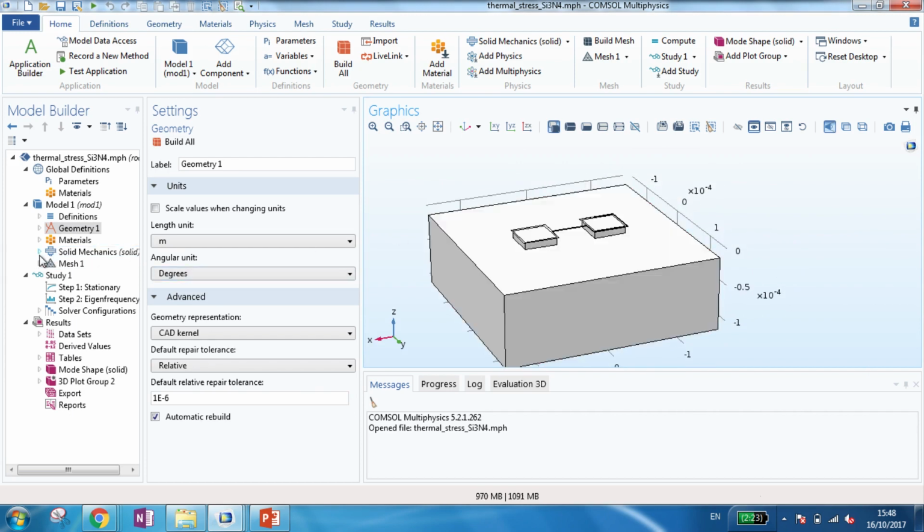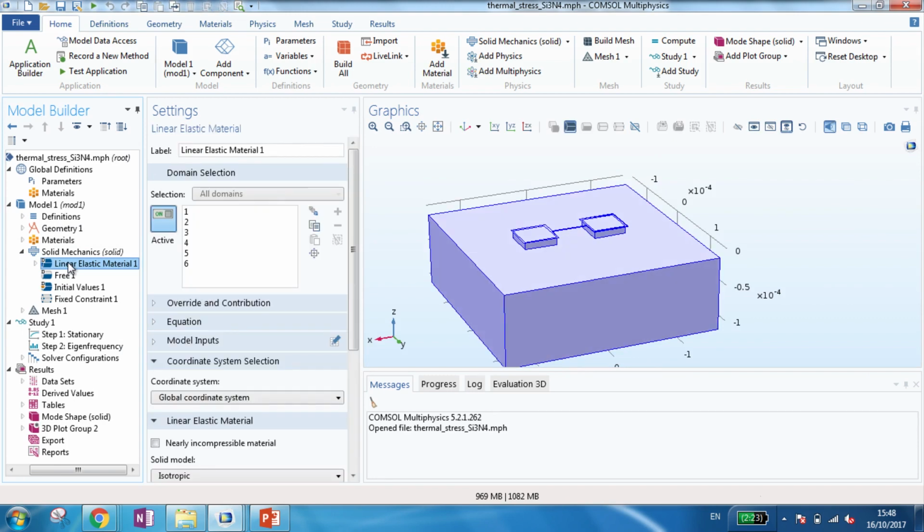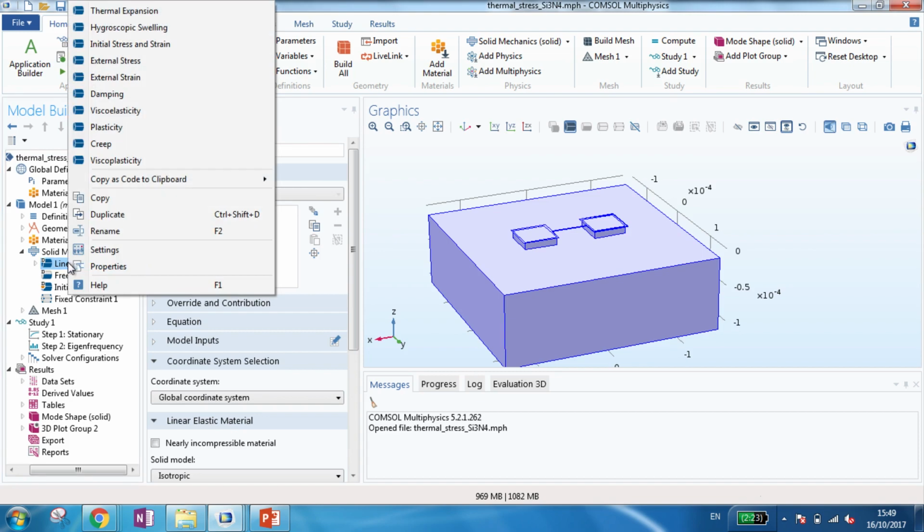So it basically cools down or heats up, depending on which is hotter. And then at the same time, it calculates how much stress or how much motion this thing will induce, how much it expands. And obviously, because one of our objects has a different thermal expansion than the other, when this thing shrinks and one of them shrinks less than the other, it pulls.